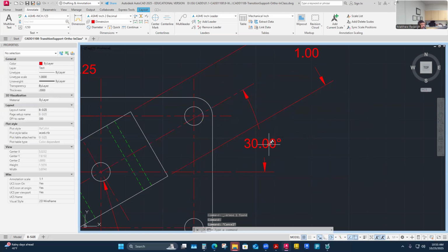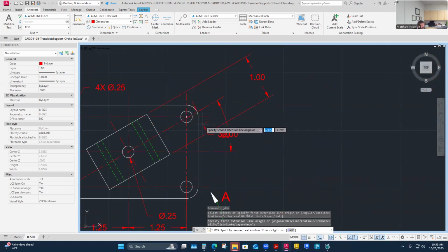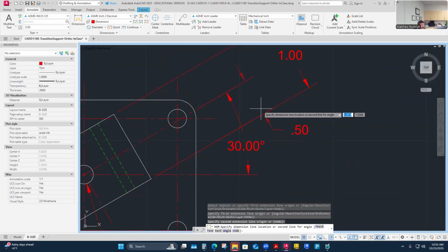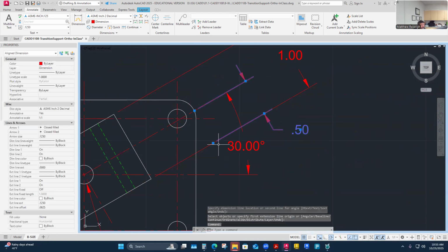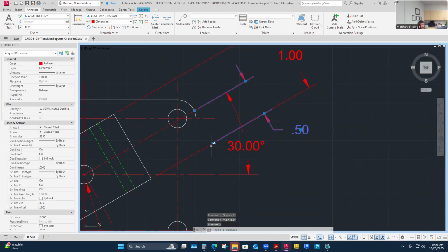Mostly because I'm catching this dimension, but I may have to tuck this in a little bit. So right now I'll use it to my advantage with that dimension and say I'm coming here where it intersects there. And then I'm going to pull perfectly perpendicular right here. And then I can pull it out. So technically the difference is this thing isn't extending to that object edge. I'm kind of fudging it because this one is. I can get away with this because I have overlapping extension lines, when really if I try to pull that to its object edge, it does that on me. Yeah, so I'm going to leave it.